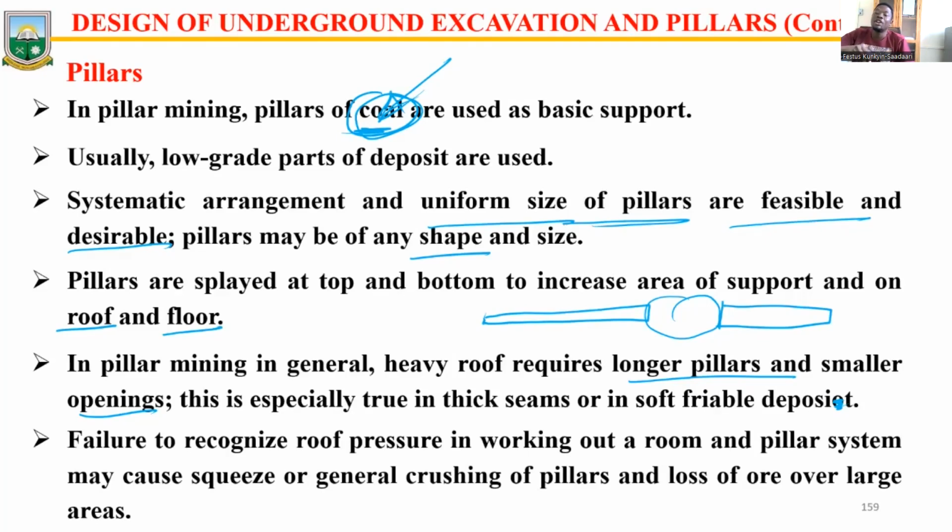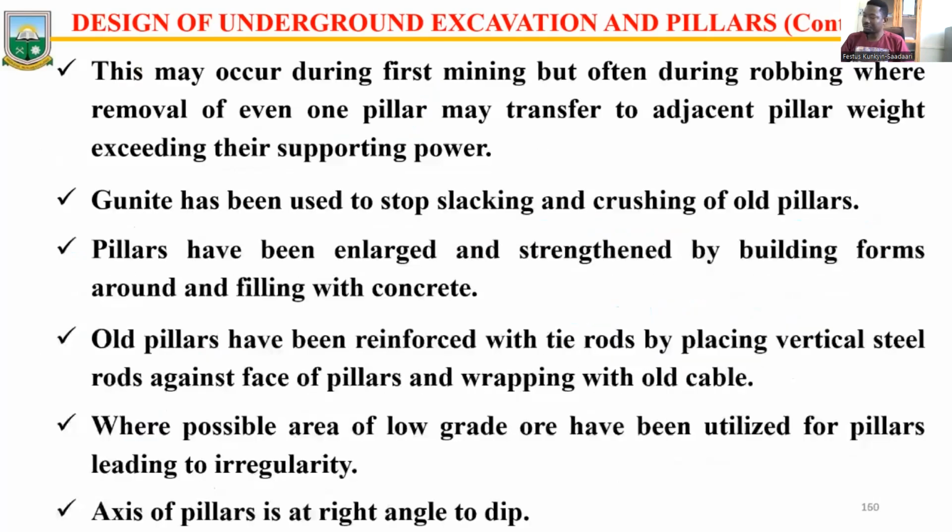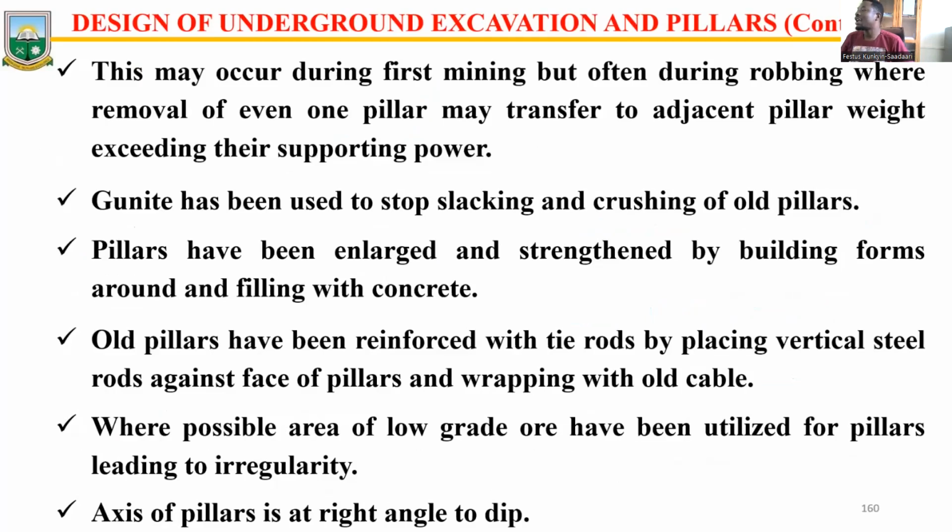Squeezing, and finally, there will be crushing of your pillars, meaning a collapse of whatever structure you have put in place. In the same way, underground, you have to check for these pressures that are going to be exerted on your pillars to ensure their sustenance. So this may occur during test mining and often during robbing, where removal of even one pillar may transfer to adjacent pillars weight exceeding their support power.